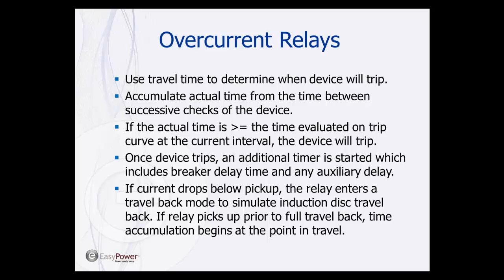For the overcurrent relay, the method that's currently used for the travel back, as far as if the pickup is reduced, follows an induction disk travel back time, and there is a procedure that's used. So it does take some time. It's not an instantaneous return. If it picks up again, it'll start from whatever point it's traveled back. So it follows an induction disk travel back.